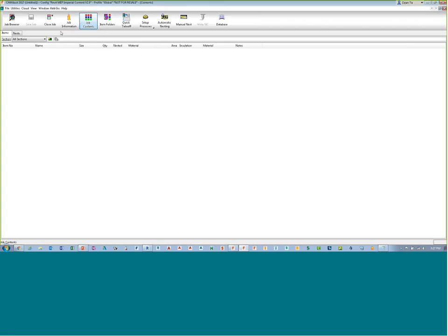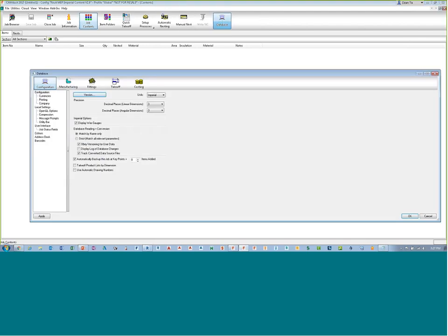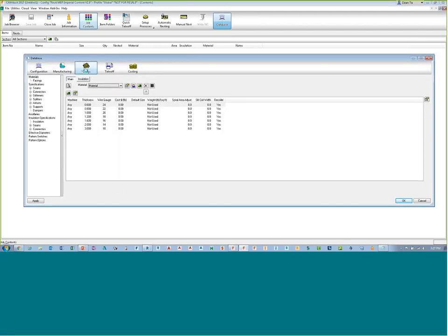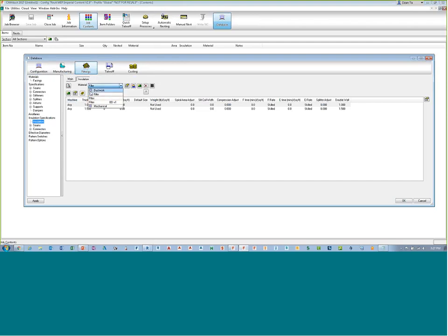No, not job information. There is a database under fittings, under installation specifications, under installation, you have all the types that are in here. So for ductwork, you have the acoustic, the fiberglass, and the thermal lag.